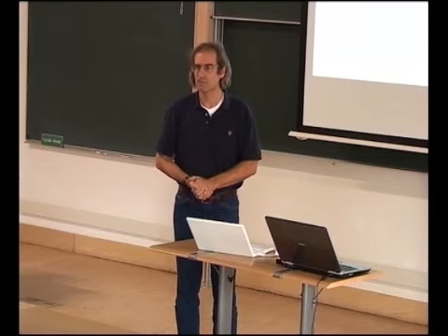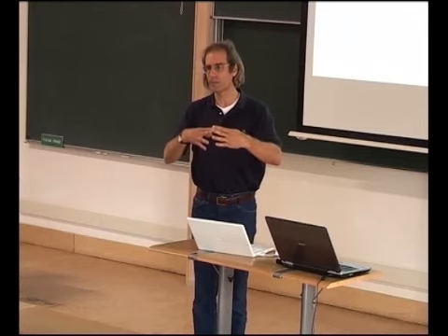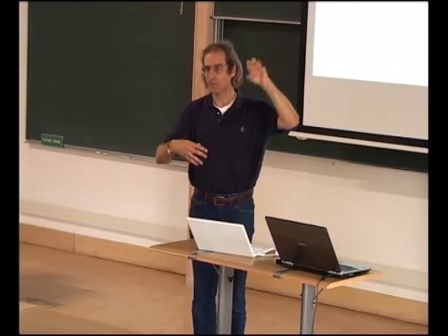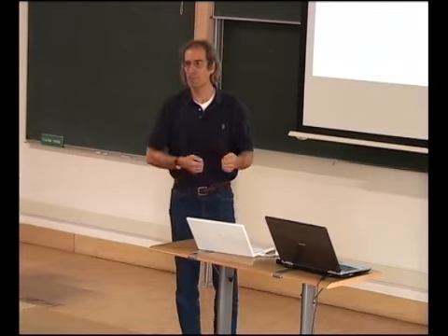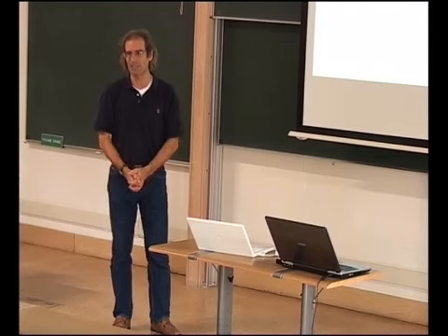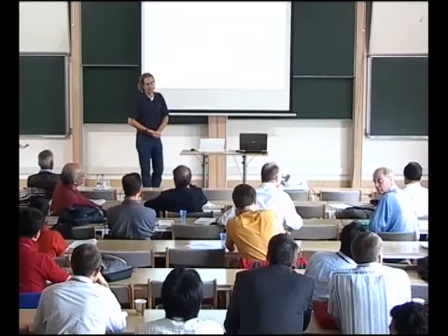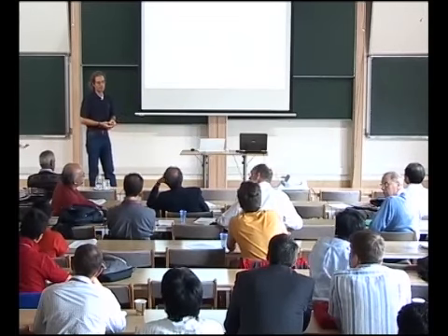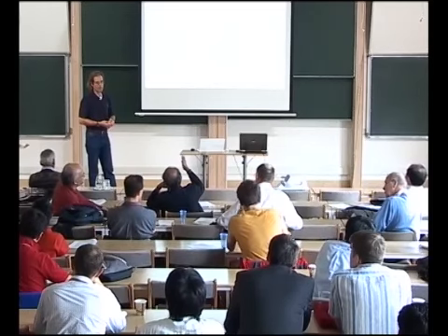This damping of the TS waves by the streaks, I guess that's similar to what Kosu Brown found. Exactly. Did you compare with them? Did you find the same? Yes, we did essentially the same thing. We did the analysis and first tested to make sure we were reproducing the results, and we see the Tollmien-Schlichting wave being suppressed, so we agree 100% with that effect. But then there's a secondary instability: once you put in the Tollmien-Schlichting wave, it will be warped by the free stream turbulence, and it's a competition between those effects, but we agree 100% that effect occurs, and that's why mode 5 behaves the way it does.